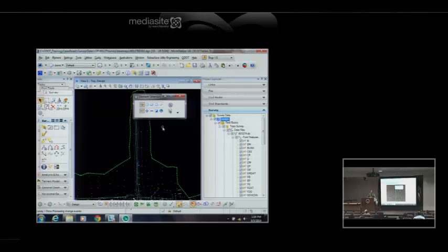Yeah, the question was, if you shot this one linear feature from two setups, one going in one direction and one going in the other direction, I would make sure they're two separate chains, and then there's a join linear features tool. I believe you have to convert it to a point list before you can join it. So if it's a dynamic, I believe you cannot connect it. It has to be converted to a point list to connect it. I'm 95% sure of that. Yes.